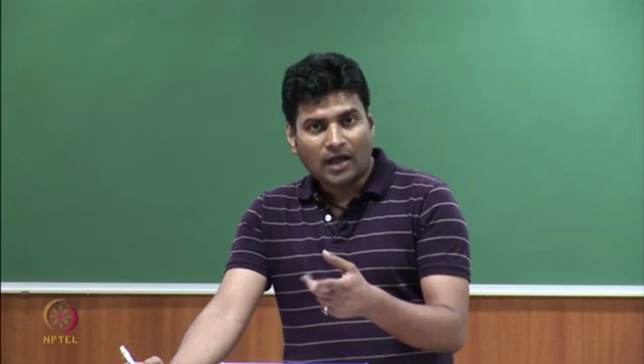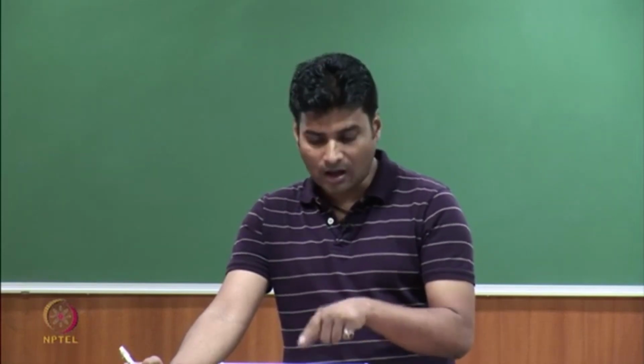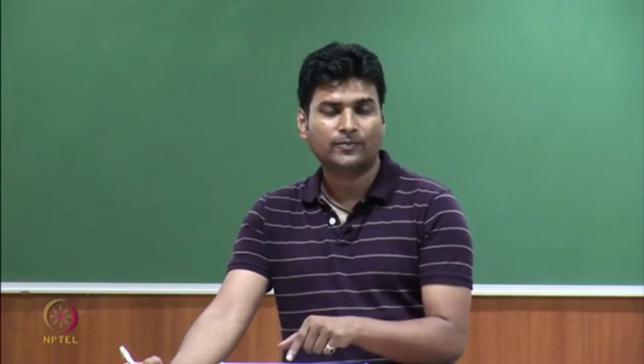since this is the r direction equation, we look for the stress components in the r direction. Therefore, we have sigma r r, tau r theta and tau r z, and then we take the derivative with respect to second index. Therefore, it is del by del r, del by del theta and del by del z.